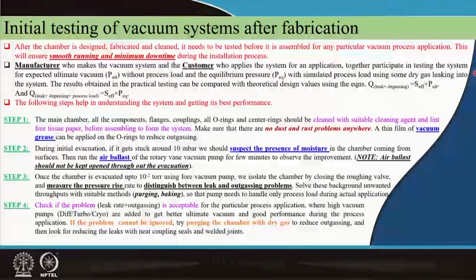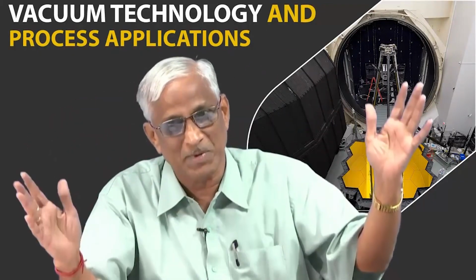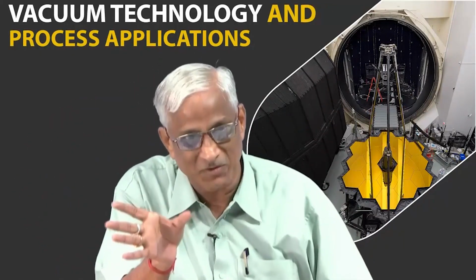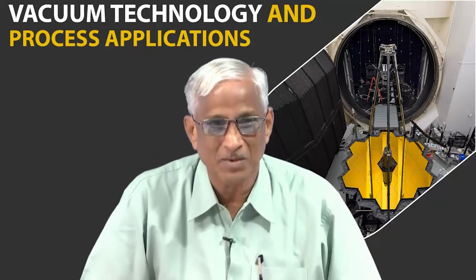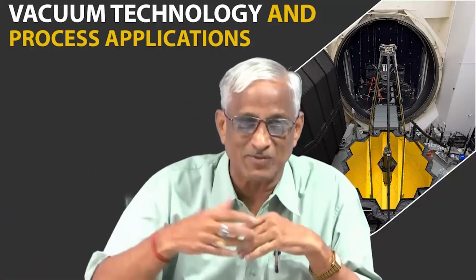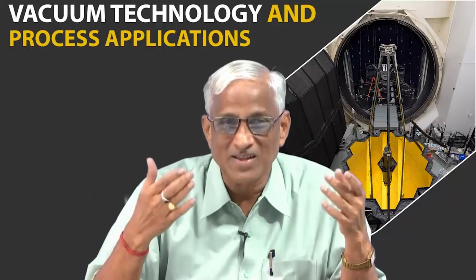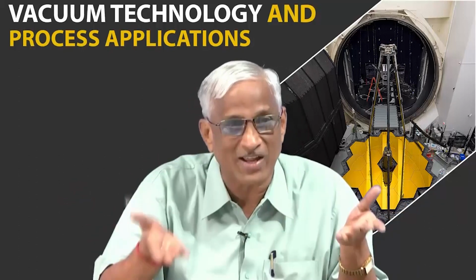And while evacuating, suppose you get only 10 millibar in the initial evacuation. Total evacuation may be up to 10 power -6, but initially with the rotary pump alone it should go up to 10 power -2, but you are not getting even that. You should not get nervous thinking something is happening, it is not at all working as per my standards, and next to you the customer will be sitting. No, it may be that one day before, it was a rainy day, or the people who have cleaned it have left some sweat or something,